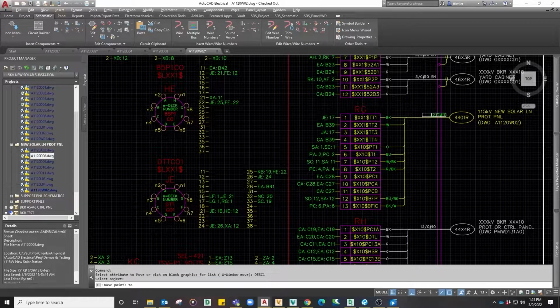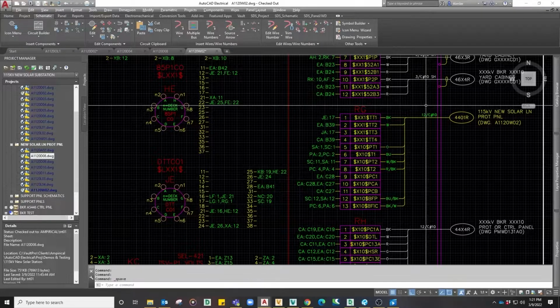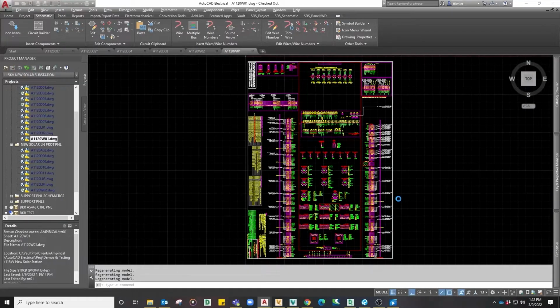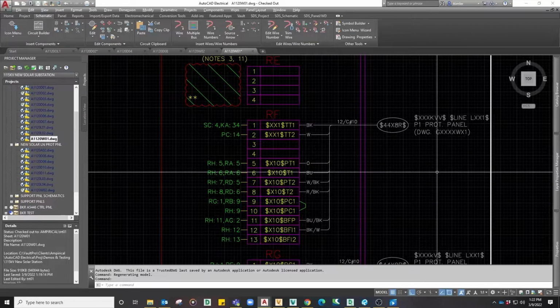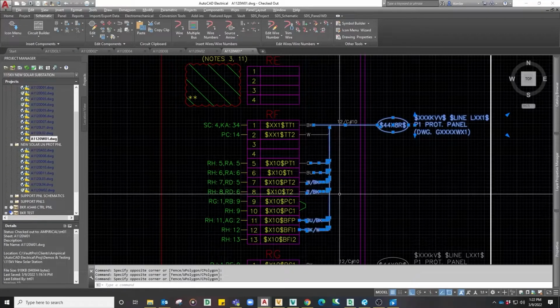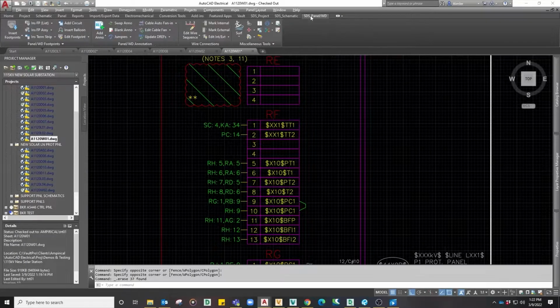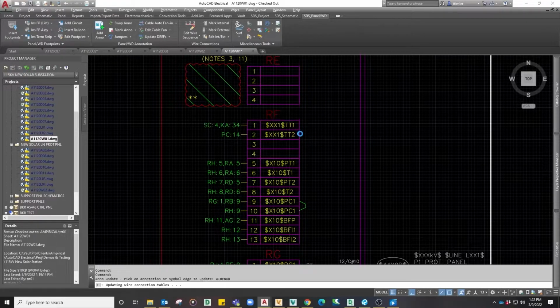Before I go back to W01 on the breaker panel, I'll go ahead and just reorganize some of these attributes and align things a little bit. Go ahead and update W01 here in the same way. Delete the template. Go to the SDS Panel WD tab, Annotation Single Pick. Just pick down the terminal strip just like I did before.